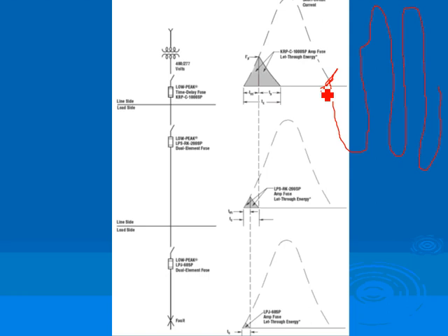The circuit breaker will interrupt the circuit, but the circuit breaker might die in the process, meaning it will interrupt the circuit, but it will not be operable after. You might have to replace the circuit breaker. That's type 1. It will survive enough to open the circuit, but it wouldn't be operable after that, meaning you have to change it.